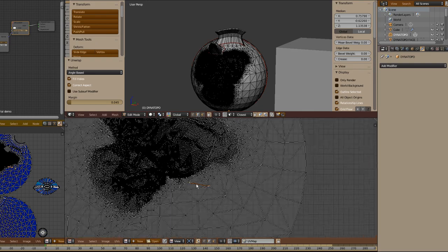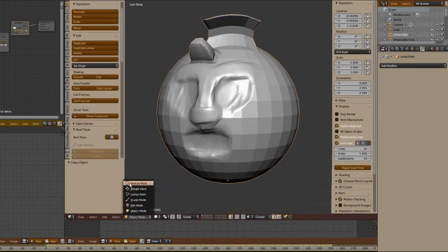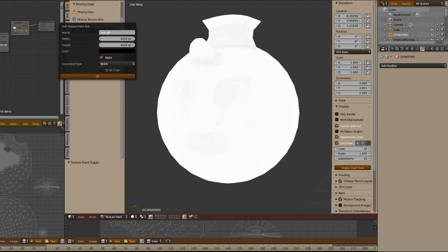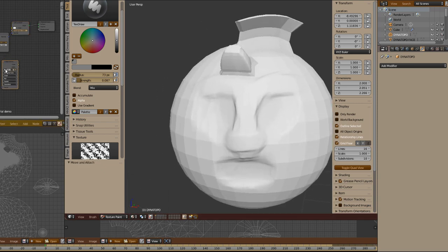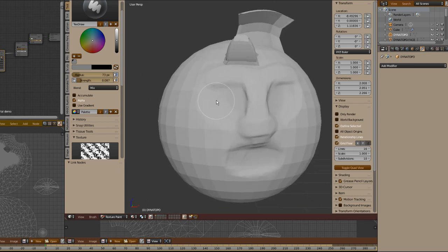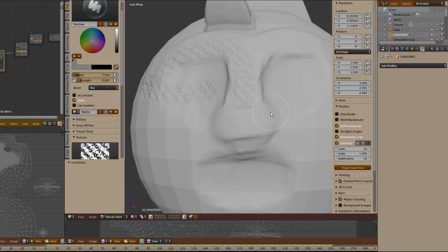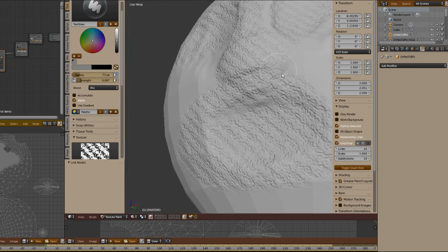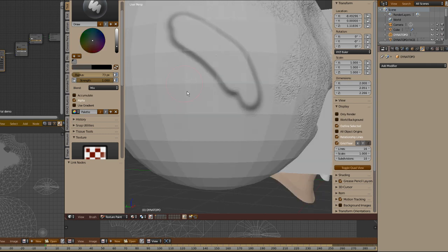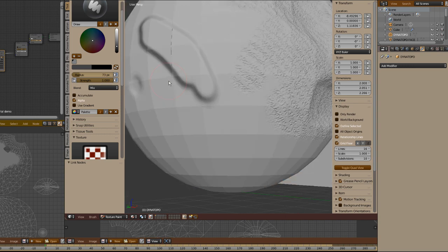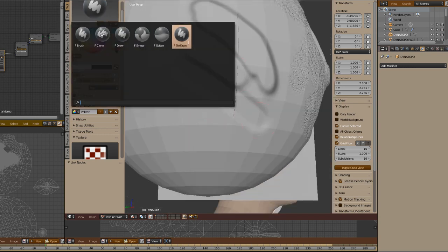With the opening of the UVs, I can, for example, at this time, enter in the texture paint mode. Now, the system is giving me the chance to create texture maps. I can paint in real time the different types of texture maps for my mesh, like displacement map, bump map, normal map, diffuse or albedo map, and other types of maps that I want to create and paint. Here in texture paint mode, I have the possibility to perform work similar to what exists in 3D Coat. There is per pixel painting, micro vertex painting, and also the vertex painting of the paint room.